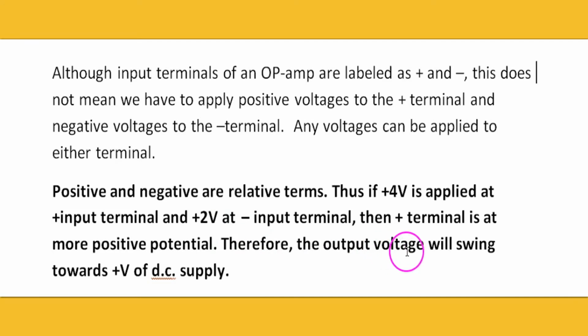Therefore, the output voltage will swing towards the positive side of the DC supply, meaning plus VCC. The output voltage depends on which input voltage is greater.